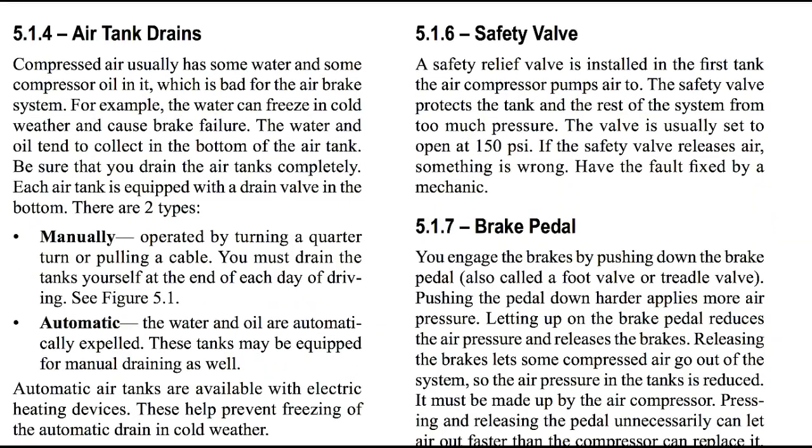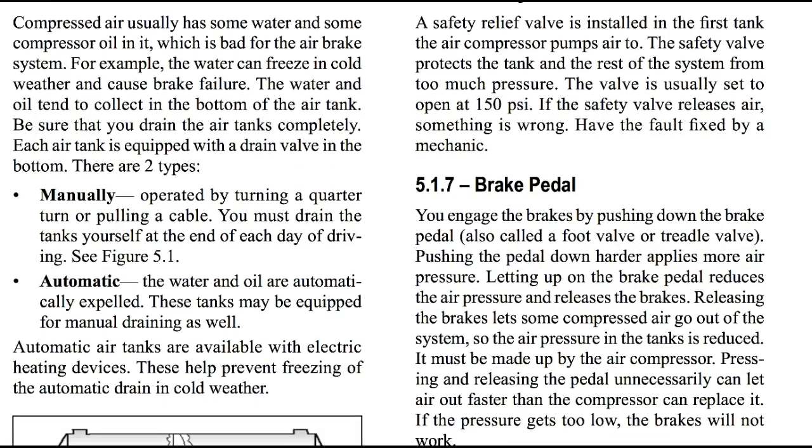Air tank drains. Compressed air usually has some water and some compressor oil in it, which is bad for the air brake system. For example, the water can freeze in cold weather and cause your brakes to fail. The water and oil tend to collect in the bottom of the air tank. Be sure that you drain the air tanks completely.